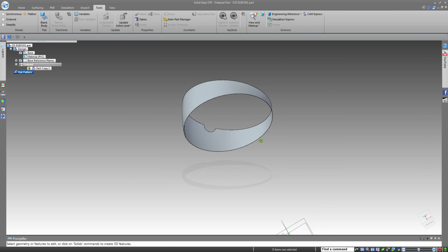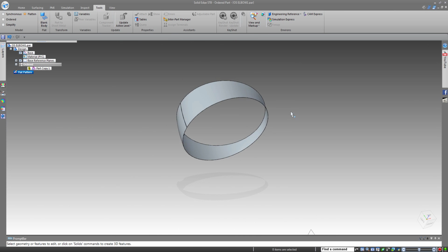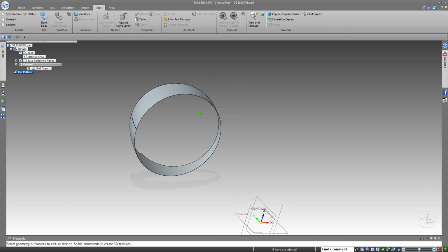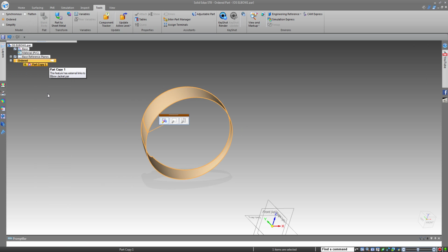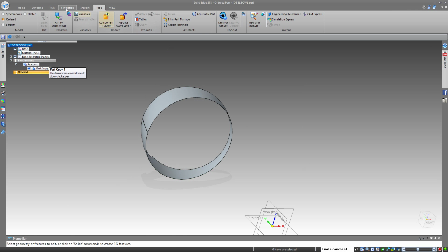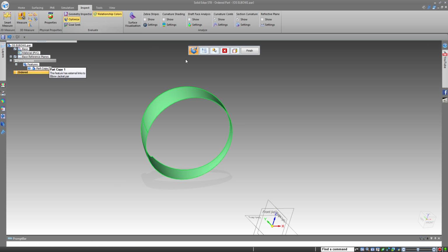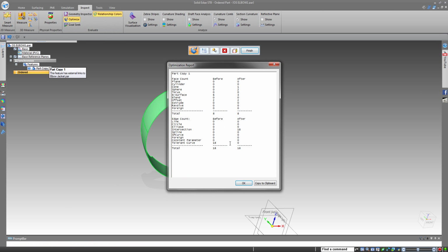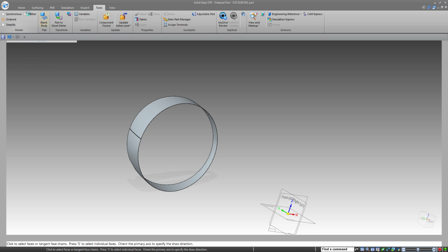Sometimes you get something that's really complex. It's typically with something with a tight bend radius on the inside or not much material, but I have found a workaround. And it's quite simple. So let's go back to the ordered. I'm going to move this to synchronous because we have a command synchronous. It is optimize button. So if I move that to synchronous and run optimization on this, and let's see, it did find a few things, cleaned up a few sections here. Say okay. Now let's try doing the flat pattern.